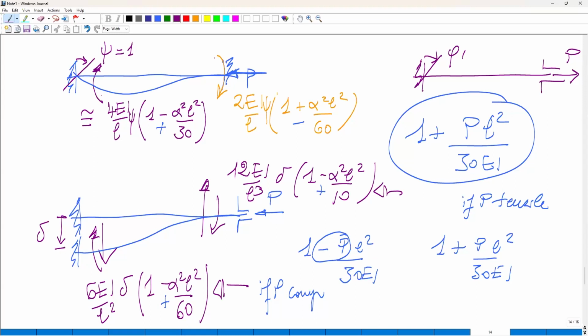So this means that this linearized theory can be used if your structure is a sway frame, or can be categorized as a sway frame, but cannot be used if your structure is a non-sway frame. So for non-sway frames, you have to keep the trigonometrical formulation and work with that. Computer programs run it and so on.